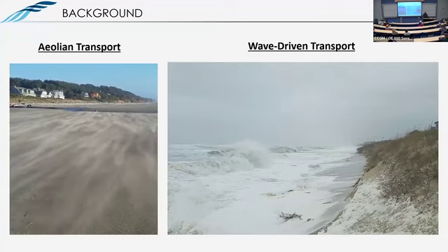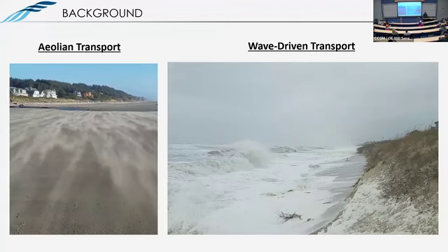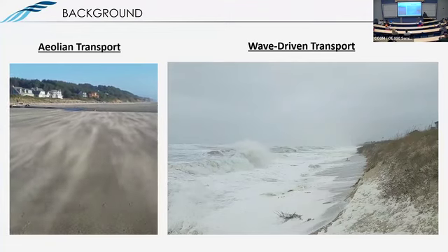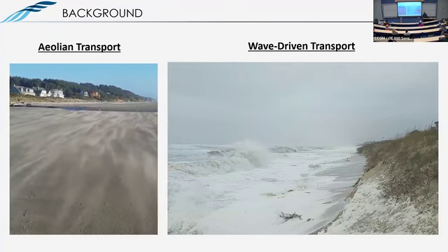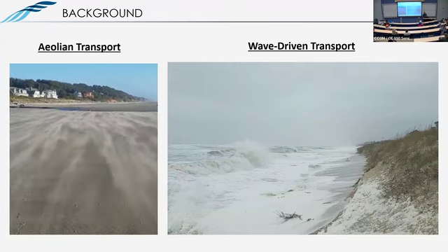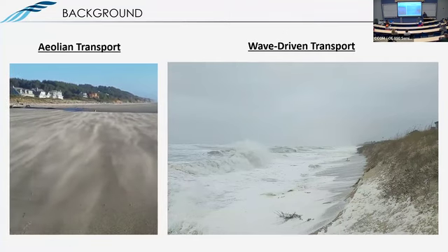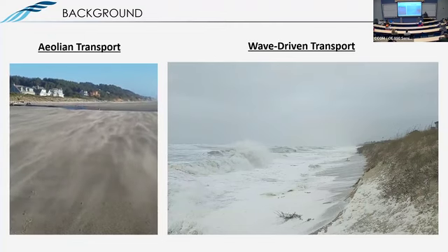Yeah, so the threshold velocity, which is basically the wind speed that you need to mobilize a sand grain, is indeed dependent primarily on the grain size, and then it's modified by moisture. And so we have empirical approaches to account for that. If you're in a fully saturated soil, it's going to be very hard to mobilize sediment. If you actually go to systems like this, this is a video from Oregon, and you can see the bed is really wet.